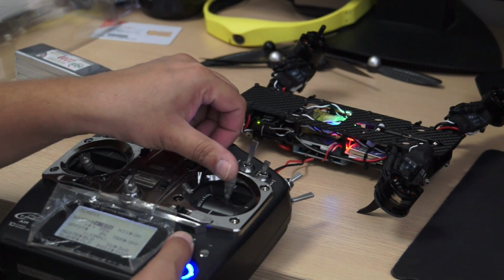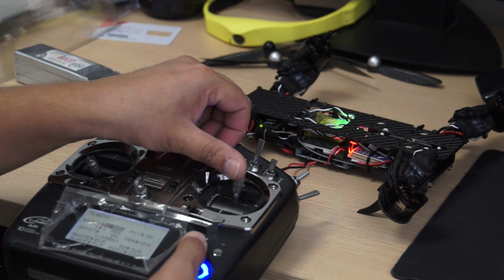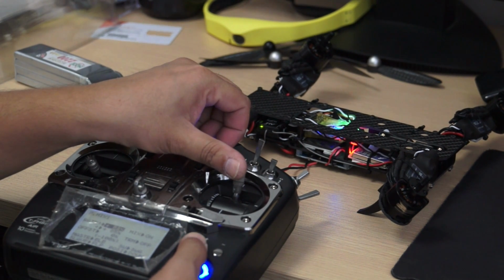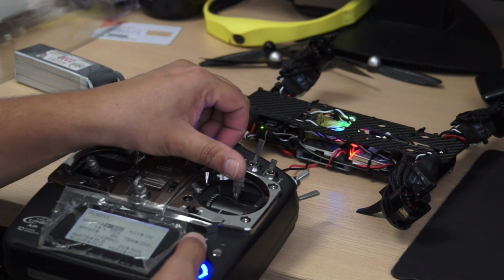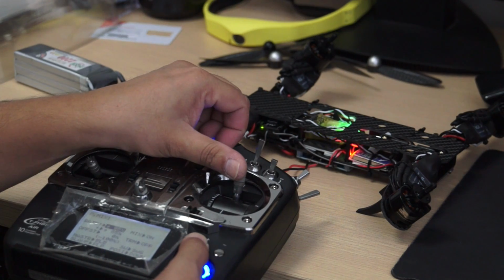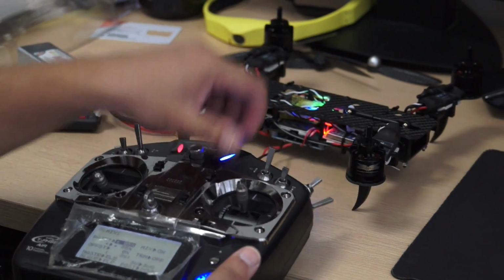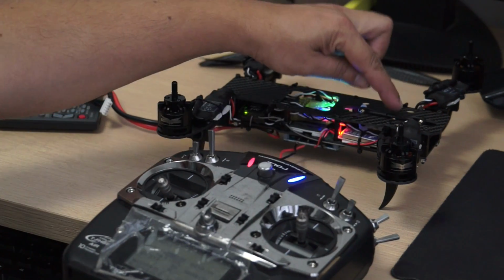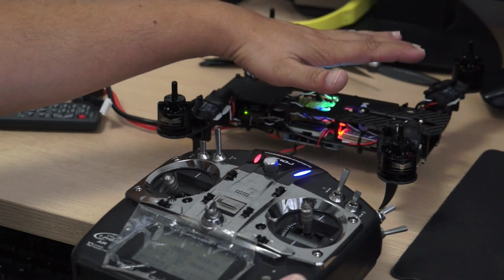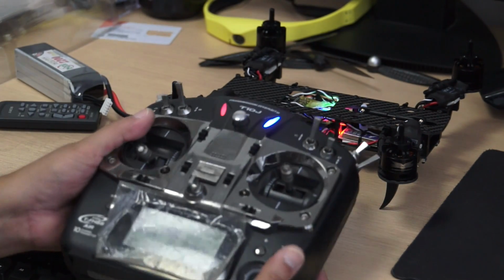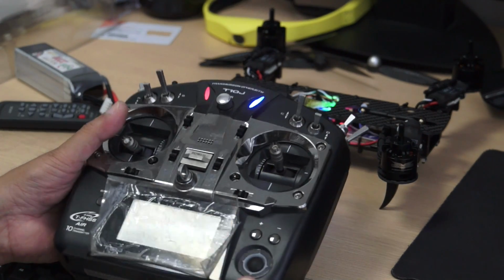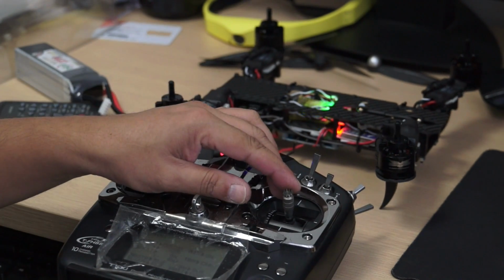The tilting is changing. So I can increase this value by holding the elevator all the way up until I find that the arms cannot move anymore. So I will set it on 95%, where it is completely safe and everything is moving to their limits, and not putting any kind of burden on the servo.